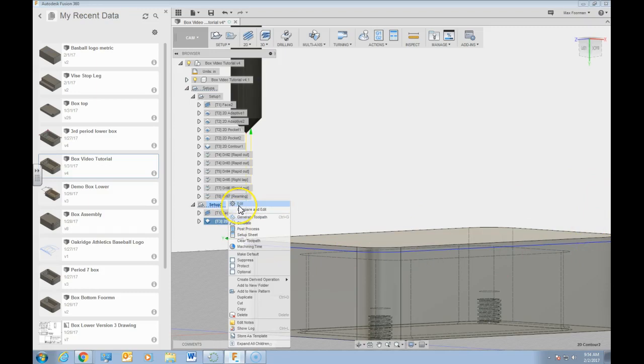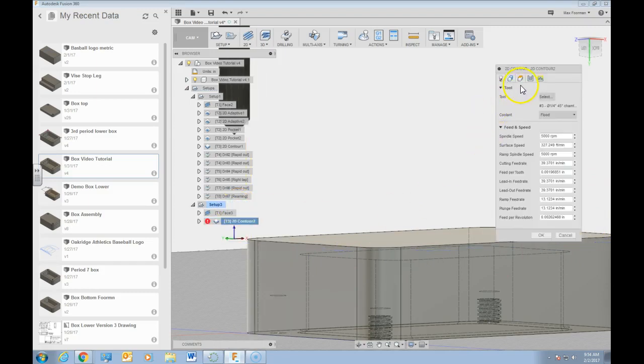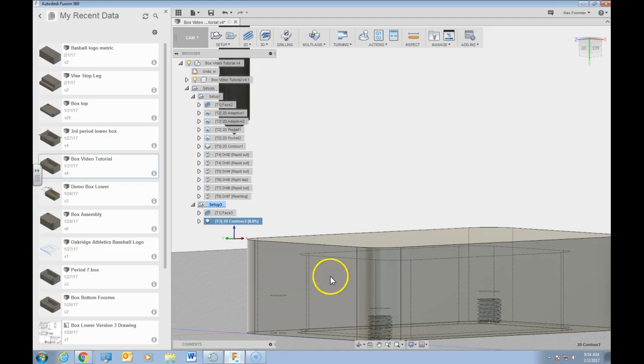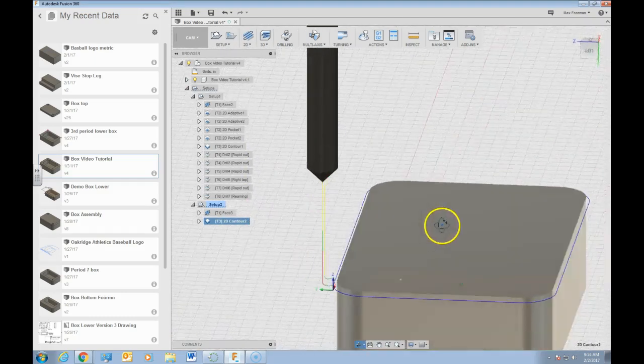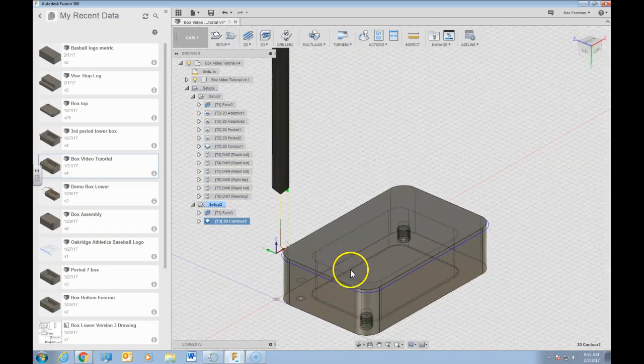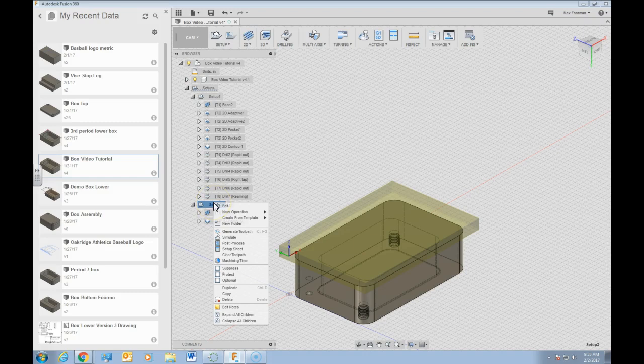The other thing that I do probably want to do, I'm going to re-edit this. So instead of passes here, we're going to do finish overlap of, again, 100,000ths of an inch, just to make sure that we get a bit smoother finish around. Okay. So again, it started its path around this point here, and it's now finishing right there, and it's going off and away. Okay, now if we simulate this whole thing, play.